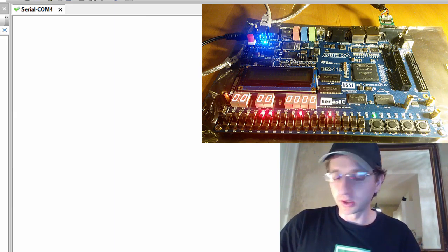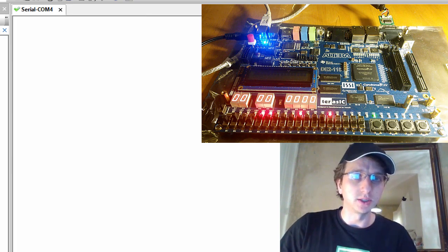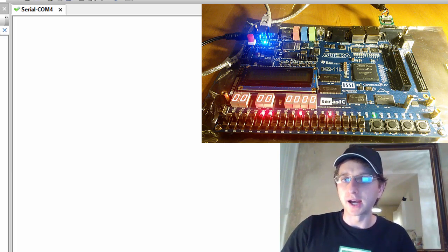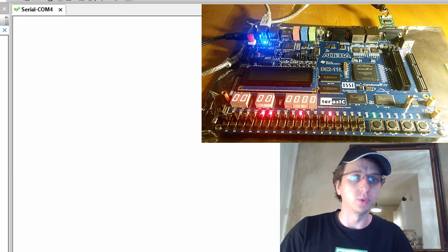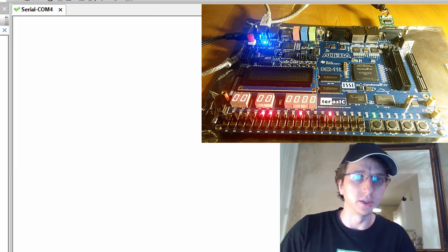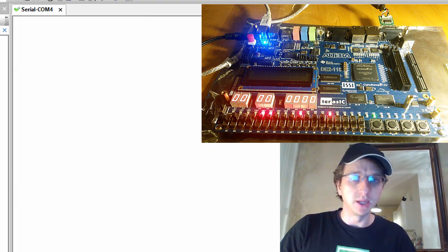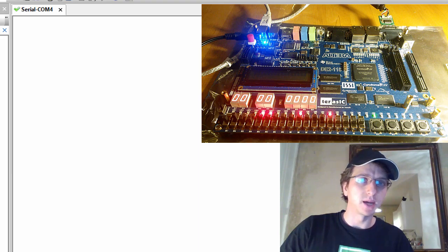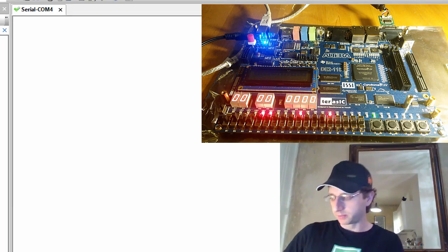So the computer is going to start off. It currently has its clock hold asserted and it's in reset mode. It's going to start off with the highest clock divide limit possible, so you can see the computer run at a really slow speed and see all of the control lines turn on and off. I'll slowly speed it up by increasing or decreasing the clock divide limit by a power of 4 until we get to full speed. And without further ado, here we go.